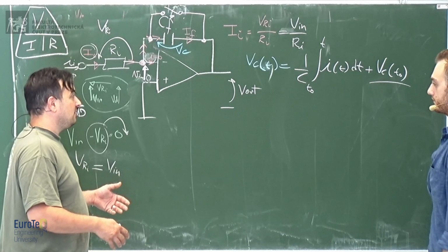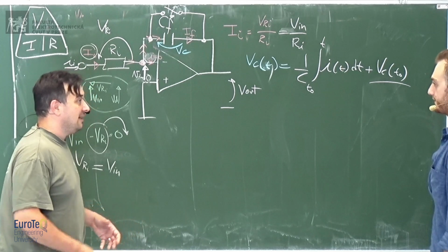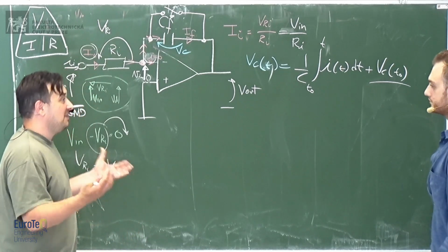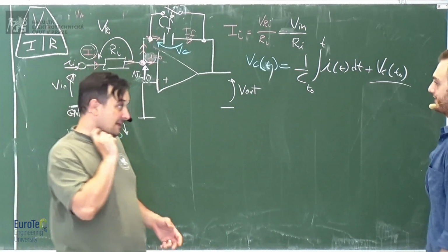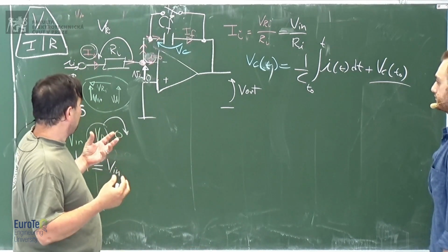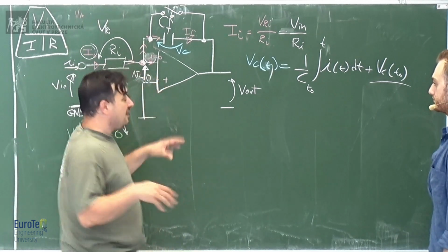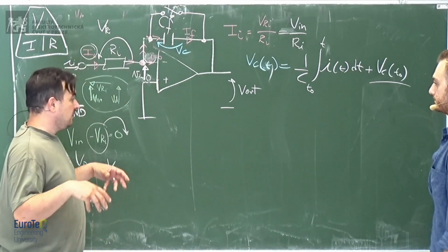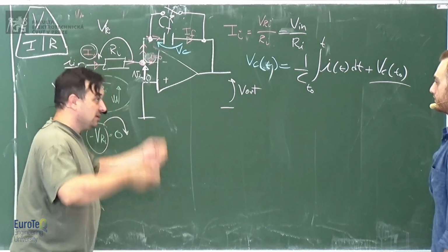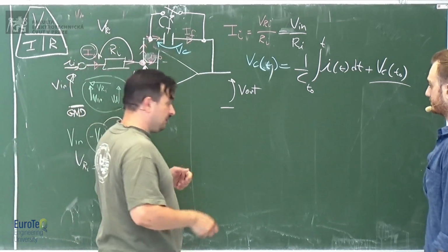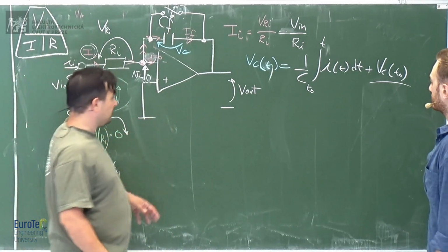But how can the voltage go from 1 volt to 0? You have to take out all the charges at once, in no time, which means you need infinite current, and it warms the capacitor up. So you always want to limit the current which exits. So you can never impose a voltage straight onto the capacitor directly. You have to charge it. So you put some current and you develop a voltage, okay?